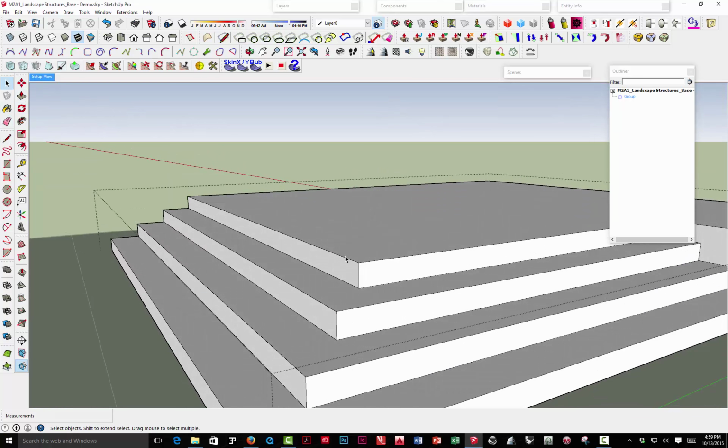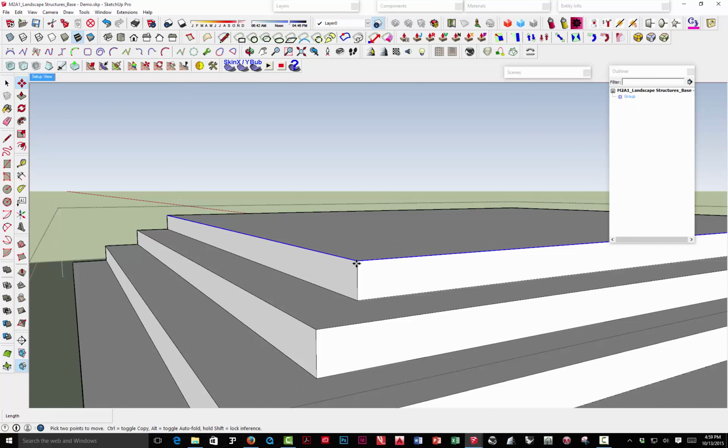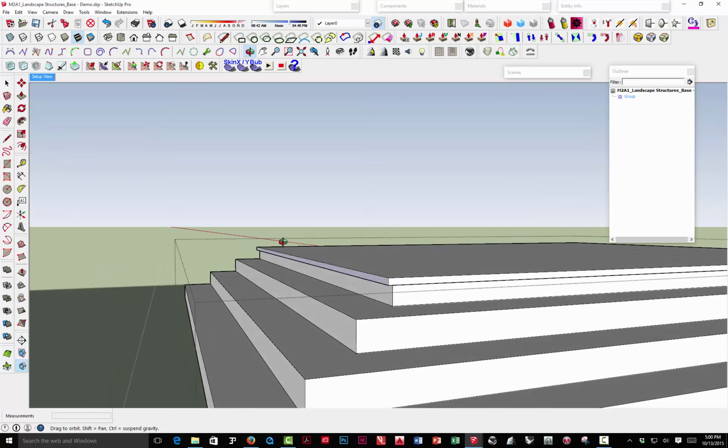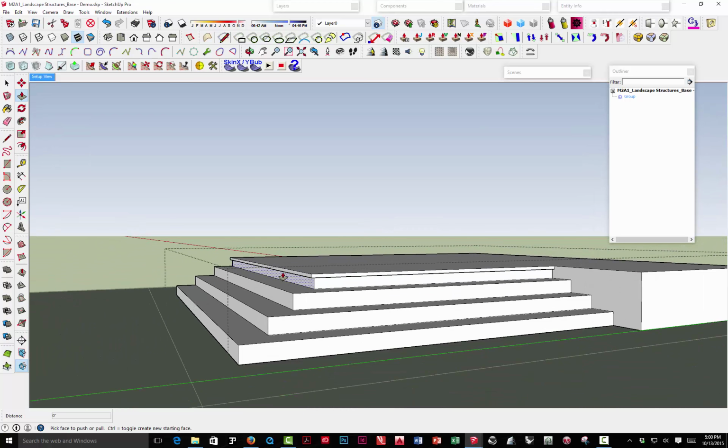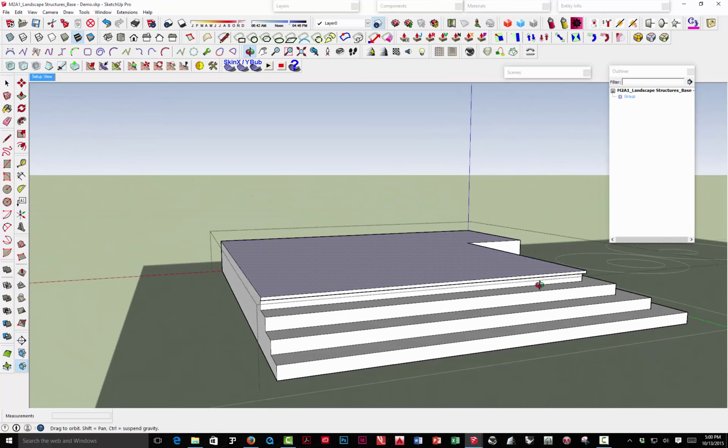So I'm going to zoom in on this, select these top two sections and use the same process. Now, as I did vertically, pull that down with the control key. There's 1.5 inches, push pull, 1.5 inches, 1.5 inches. So that's what I want you to do. I want you to go through. Now, I just did it on this example. I just did it here.